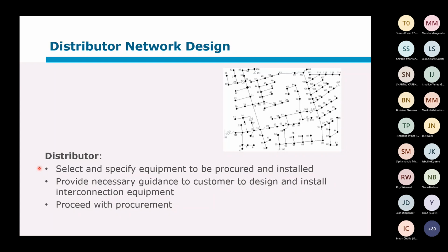So that is, planning said it's a 132 kV line. It needs to be able to carry 200 amps. And we now select, okay, planning would have selected the conductor already. Design is going to say, all right, we now need these towers, we need these isolators.